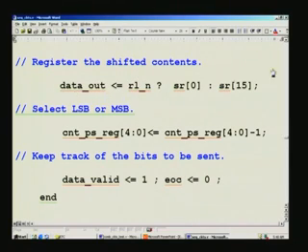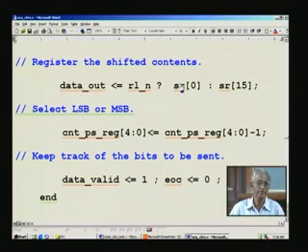What we have seen is a shift register used internally, that does not come out as such. So the output you have to route to the actual data out, and that is what we do once again based upon the right or left shift here. If it is right shift, we have to assign SR0, because when you right shift, the LSB will be sent out first. That is what is being done here, and that is being sent to data out.